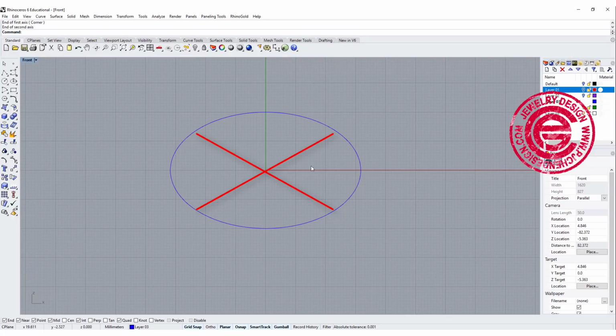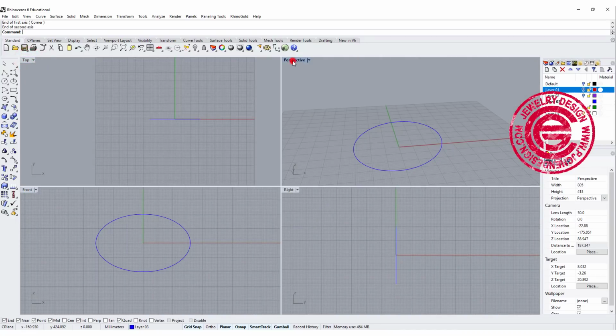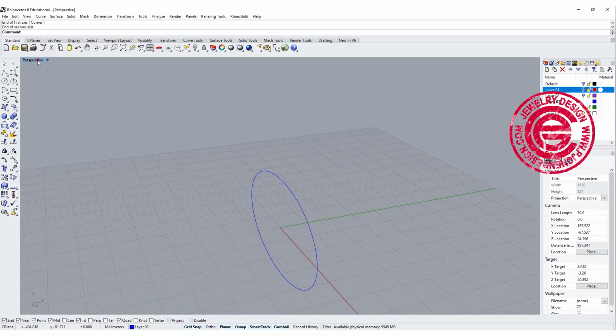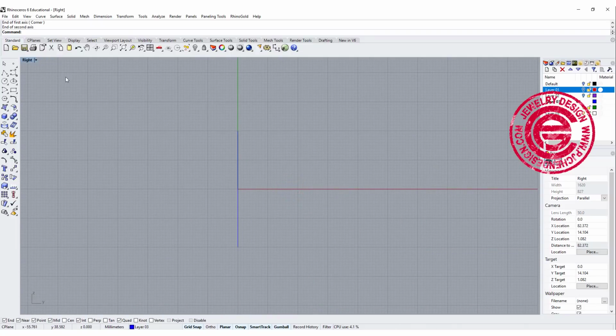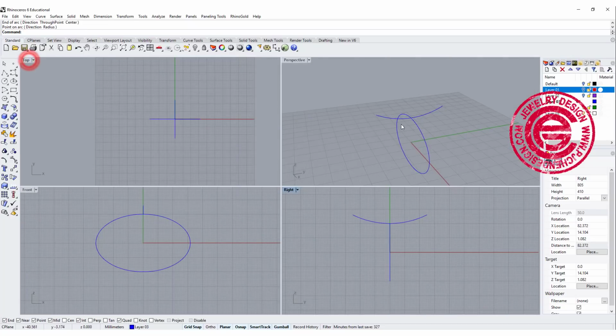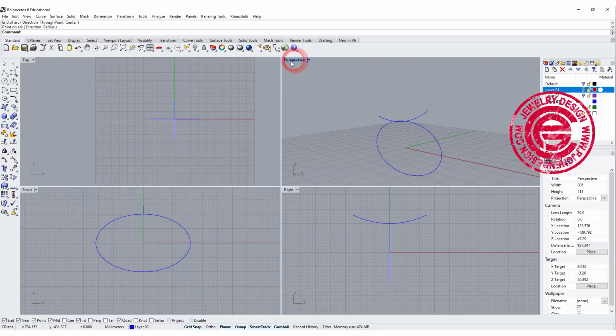We want to design everything outside of this middle area, and that's starting by doing a profile. In this profile, I'm going to look at the right view, and then I'm gonna decide it with the arc. The arc that I'm going to use, I'm gonna turn on a grid snap, and it depends on how deep you would like this one to be. I want to make something a little bit wider, so I'm just gonna go over there and count the same number on the other side and have the middle come over here. So right now I have something that looks like this in the perspective.